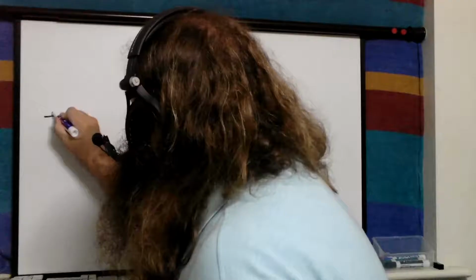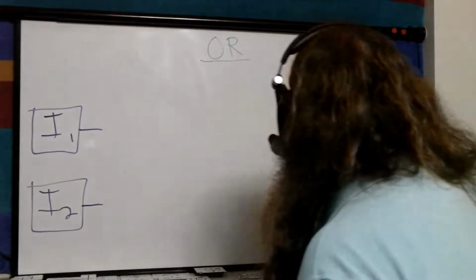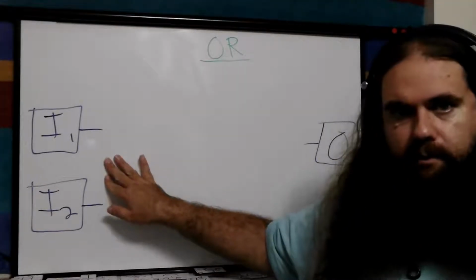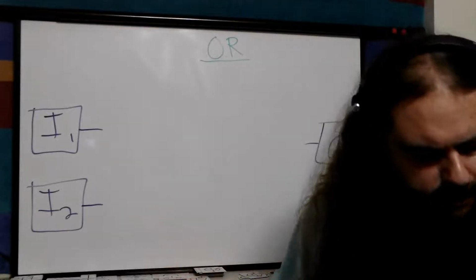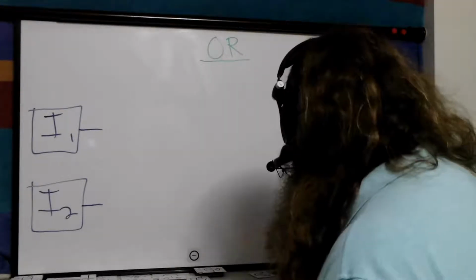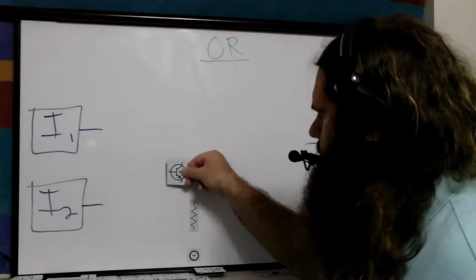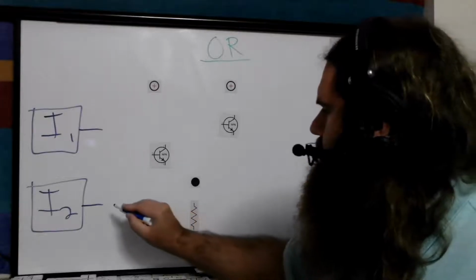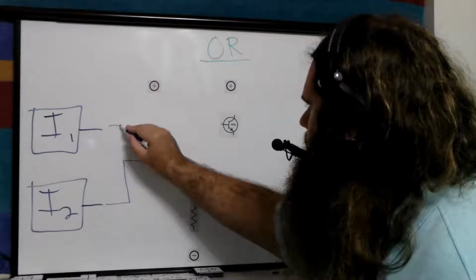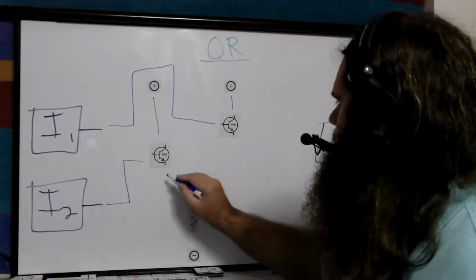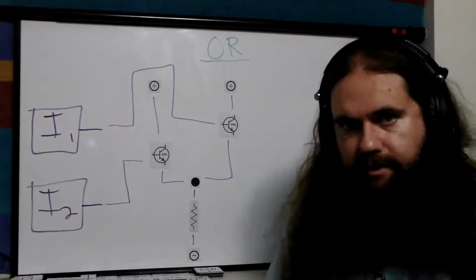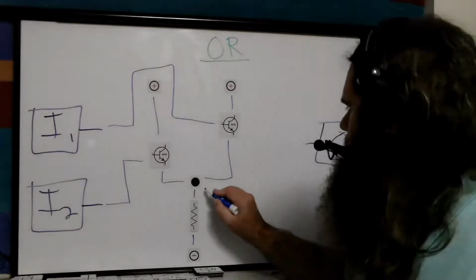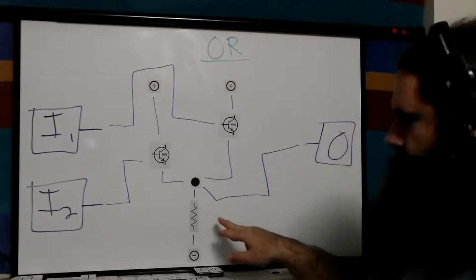So what about this circuit? We have input 1 and input 2, and then our output. And now, of course, we'll use 2 transistors because we have 2 inputs. And once again, we assume these are well behaved. If they're not well behaved, add resistors. So down here, we have negative power and a resistor, 2 transistors, one over here, and both of them are connected to the positive. The inputs go into the transistors, just like before. Power through the transistors. Output joined through a resistor afterward, so effectively high side switches with NPNs now. And the output actually comes out of here, between the transistors and the resistor.